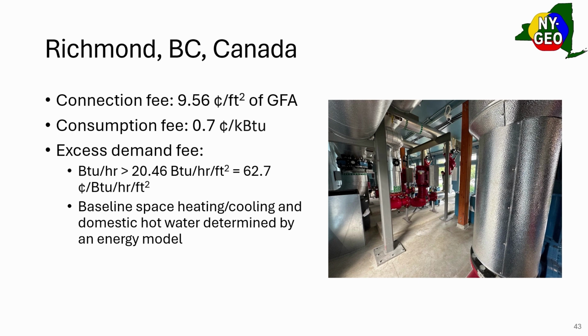And then they have this excess demand fee, which is pretty interesting. How this excess demand fee baseline is developed is a professional engineer in British Columbia, a licensed engineer, will develop a building energy model for every off-taker that wants to join the loop. That building energy model will set the baseline of the space heating and cooling loads, and maybe also domestic hot water, or if there are other process loads on the system.